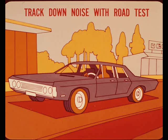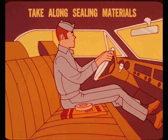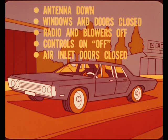The best way to track down the source of wind or air leak noise is with a road test. Besides, road testing also lets you check any corrective work you've already done in the shop. The ideal testing route is an open, low-traffic area where you can drive the car at cruising speed and pull over for tests or adjustments. Be sure to take along sealing materials and masking tape so you can isolate noise sources and make corrections on the test run. The antenna should be down all the way, and all the windows and doors closed tightly.